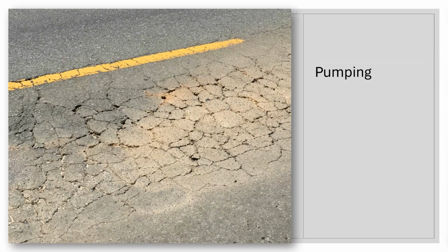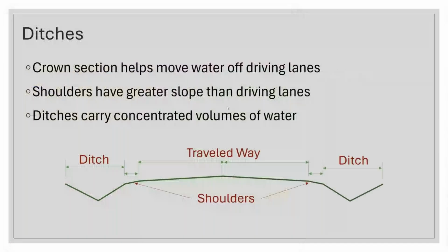Now it's just like loose puzzle pieces that happen to fit together, but as soon as you have a lot of water that pumps up through the bottom, it's going to push those loose. And when you have traffic that goes across, a semi is rolling over that and it's saturated, that water is getting pushed around in those open spaces, and it'll pop some of those sections out, and now you've got a pothole. So anyway, lots of things we could talk about there, but our focus today is going to be on the pavement design part. So let's get back to that.